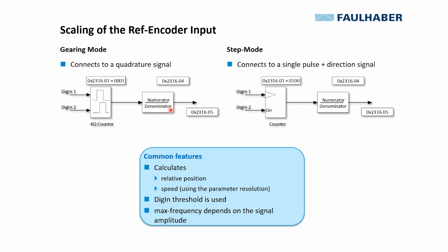Usually it's position control. So for example, in my demo unit here, I'm having with these linear Hall signals 4096 increments per revolution of the motor. And with my DC motor being the reference here, it's a 512 lines per revolution encoder. So if I want to have a one-to-one movement, one turn of my reference and one turn of my motor here, I would have to rescale the 2048 counts out of the quadrature signal into the 4096 that I need for my brushless motor.